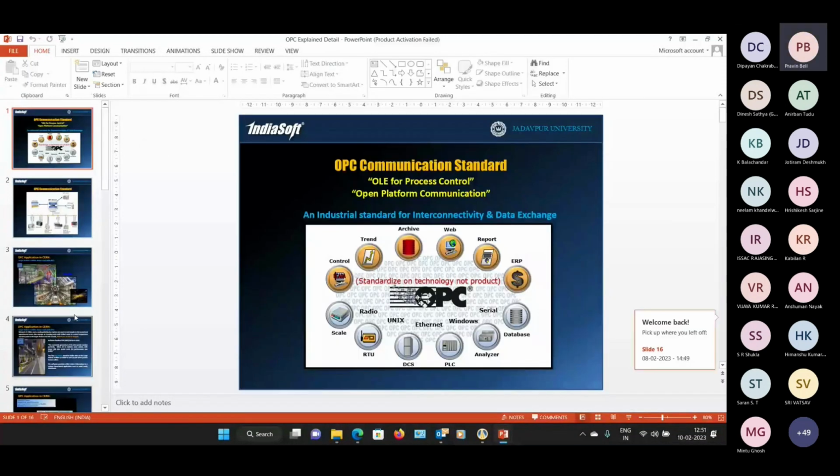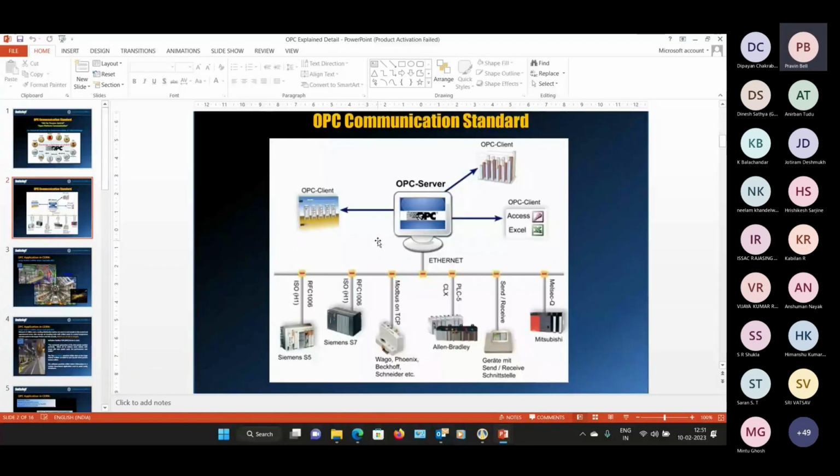So in OPC, on an Ethernet cable, there's an OPC server residing somewhere on that network. Okay, you can connect OPC via Ethernet cables. Then that acts as a data exchange server, and that can connect to even things like Microsoft Access databases. You can log data there. You can communicate with PLCs. You can communicate with any of the processor boards from Dynalog, Siemens, Beckhoff, Schneider.